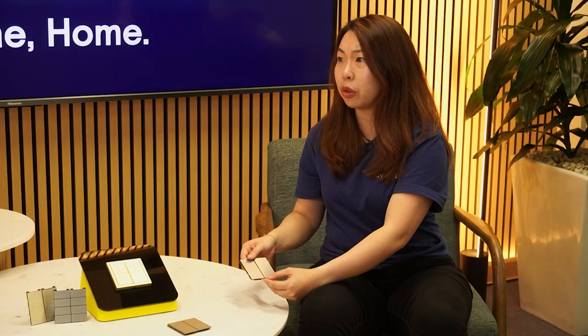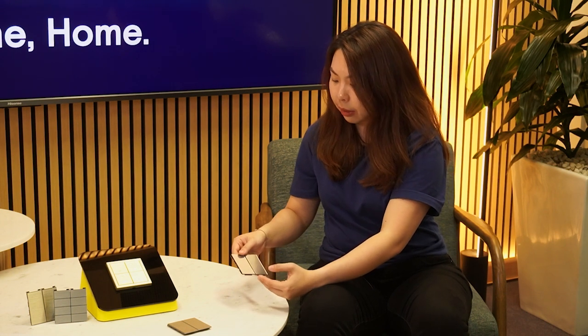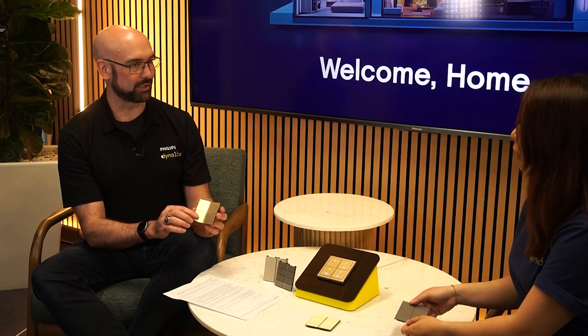What exactly is that? So PVD is short for physical vapor deposition. It's a technique that transfers metals to plastics. What we are seeing here is that the metal is vaporized into particles and transferred onto plastic in a vacuum chamber. Oh, wow. So the finish that we're seeing here is the result of real metal being applied to a plastic surface while retaining a textured surface that you also require. The reason why we picked PVD is that it gives a more stable color, and also it is resistant to wear and tear.